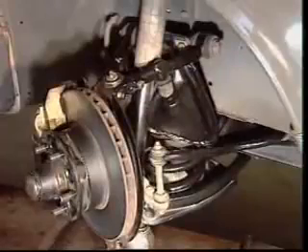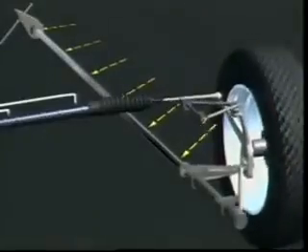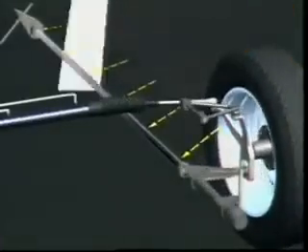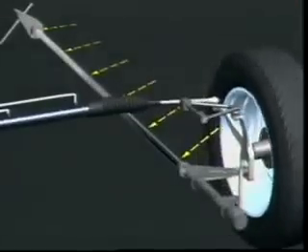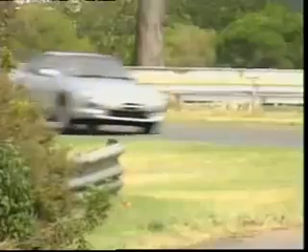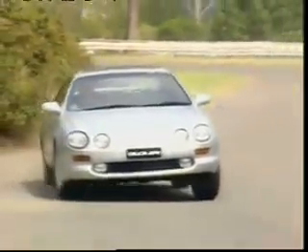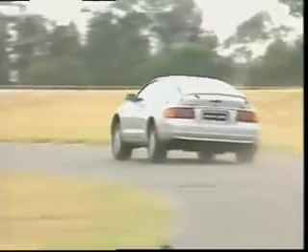The upper link is shorter than the lower one, irrespective of the springing method used. When the suspension is deflected, the unequal lengths allow the track of the vehicle to be maintained near constant, but with some changes to camber angle. Generally, when the car leans during cornering, the inner wheel leans outwards at the top, and the outer wheel leans inwards. This helps to maintain maximum tire contact with the road surface.